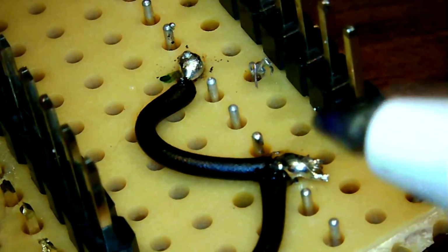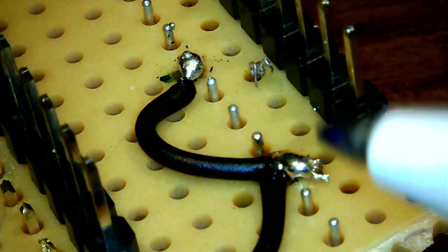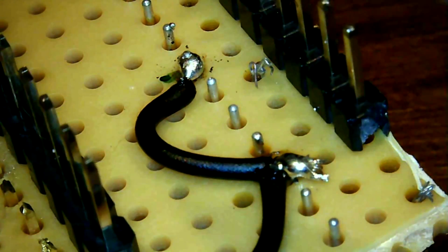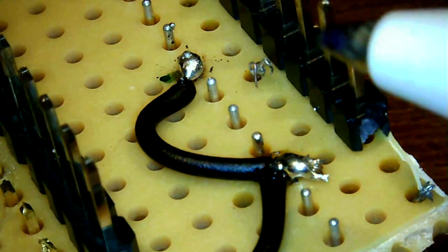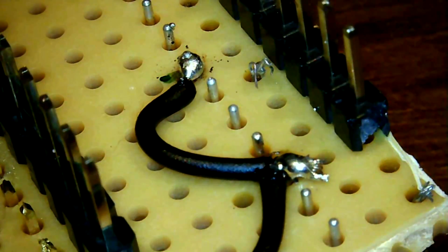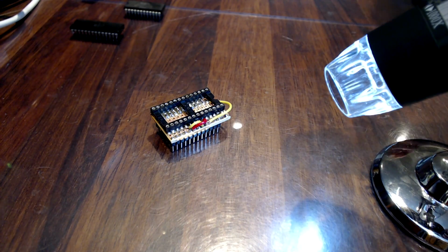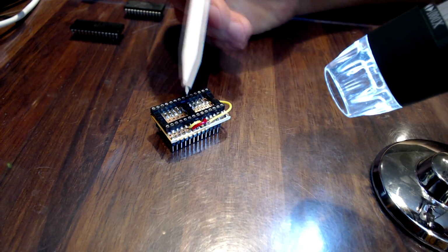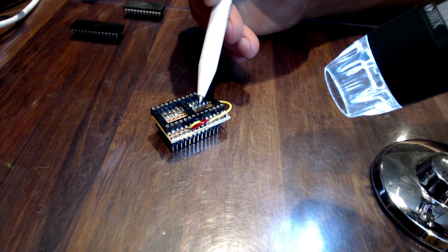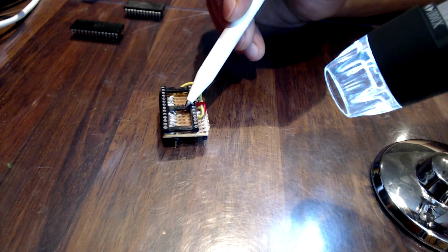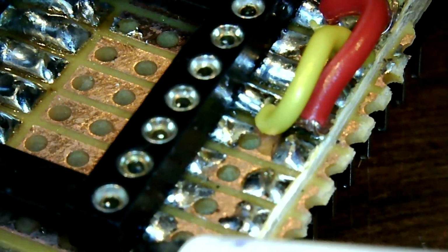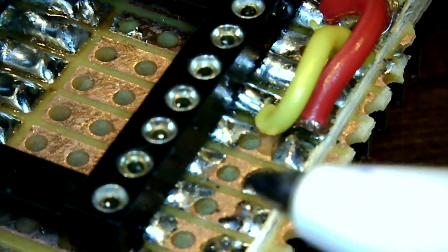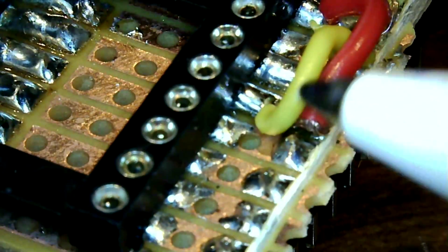This is address pin 13 and the OE pin on the EEPROM. They're tied to ground as well to prevent any issues with the address bus or the OE pin. The tough part in making this is the short wires, and there is not much space in between. As you can see here, I offset the headers by 2 pins to allow myself some more space, but it's still hard to do.